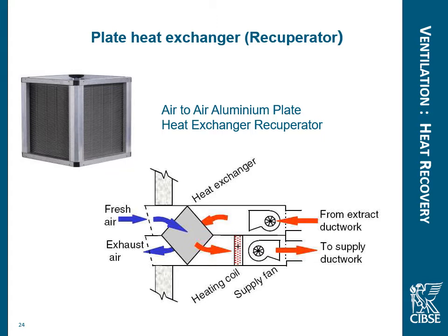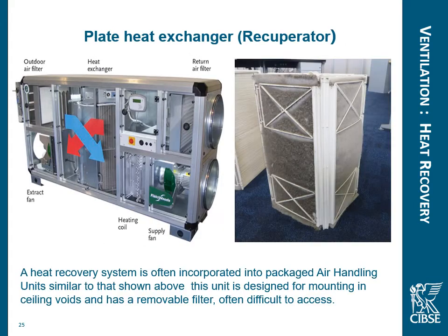Because we're losing 20% of the heat, we quite often need to have a little bit of a heating coil or a booster coil in the supply network, just to retemper the air so we're not blowing cold air down people's necks.